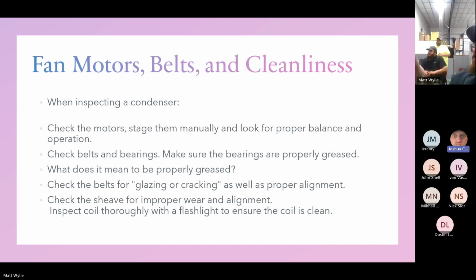Oh yeah, I just wanted to comment on that water cooled. Just another thing to check is your differential between your inlet and your outlet. Just to verify, you're probably going to be in the 10 to 12 degree change, which is just a rule of thumb.